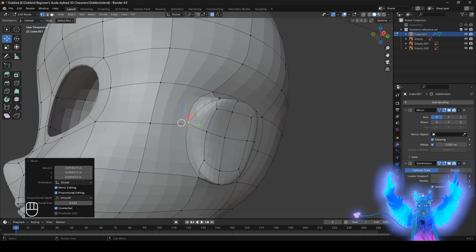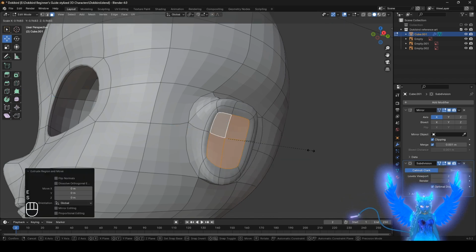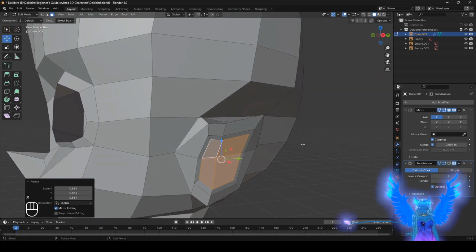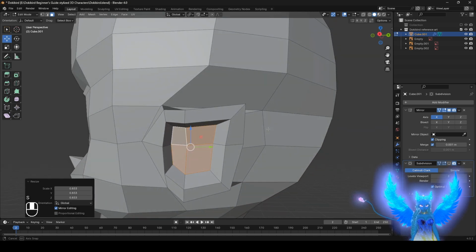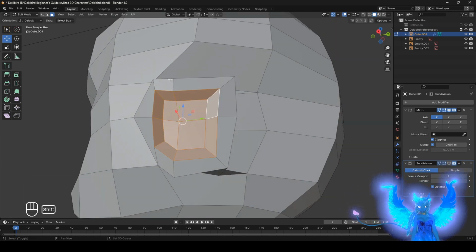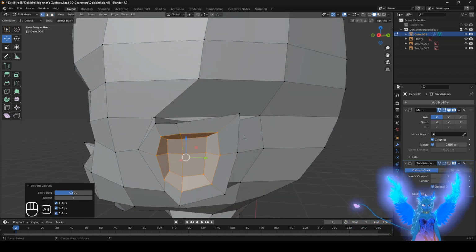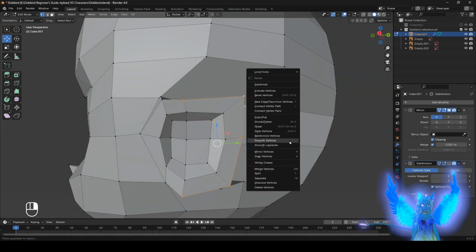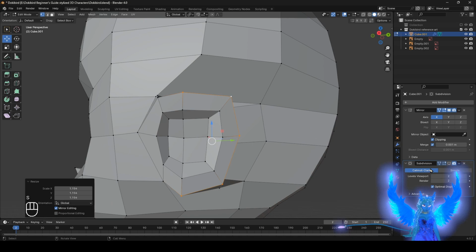Then after that, let's start morphing. Select all these, select this off, E, right click, let go, S to scale, click this off, see what we're doing, Alt S. So this goes way in. Also select all this, Alt Shift, and smooth vertex, just to get rid of the rough edges. It's just really sharp. I don't want them that sharp.